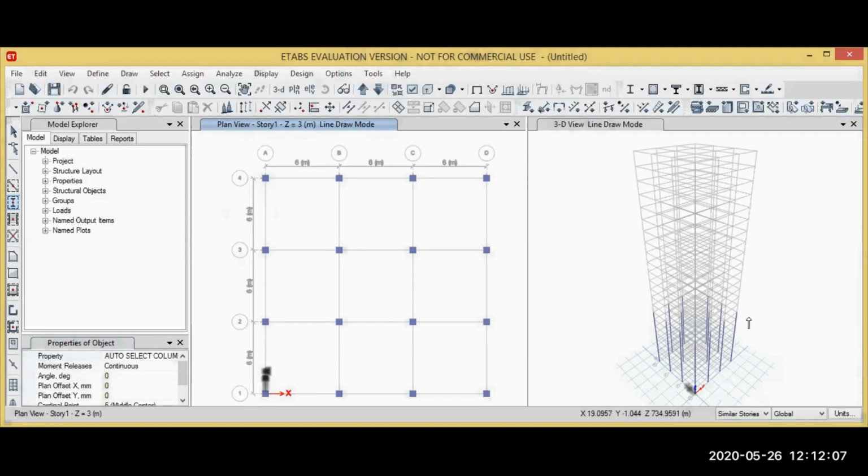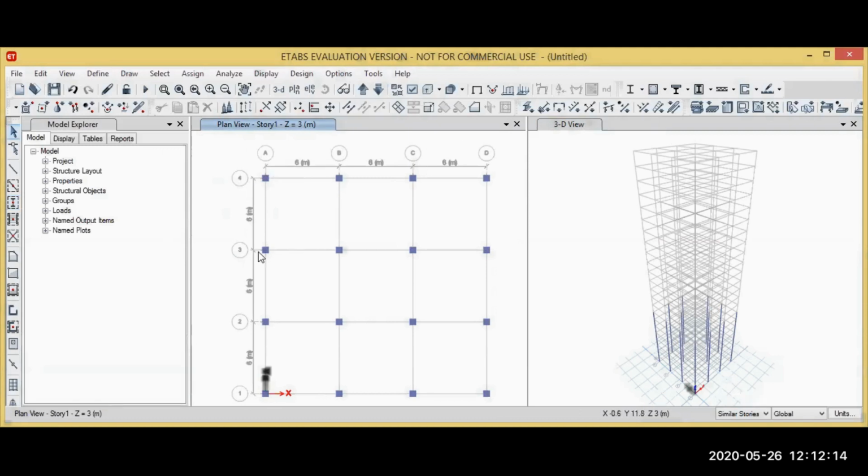You can see from our 3D. Now next, hit on escape to exit. So this, you can see it define the column, or it add the column from the base up to what we call story 8, since they are all similar. Now in order to move up, we move using the arrow to story, any story between 9 and 14. So let's go to story 9.